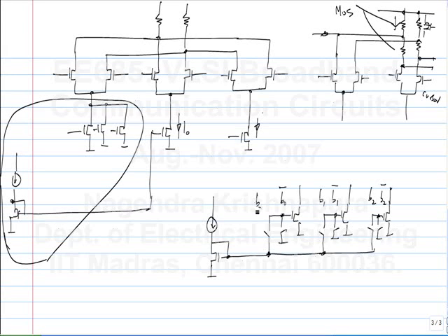Depending on whether these logic levels are high or low, you either turn the current source on or off, and you connect all of the current sources in parallel, and you don't have to have 3, you can have a large number. Okay. So the total current here will be the number represented by B0, B1, B2, times the current of each unit cell. Okay. What kind of switches will you use here?